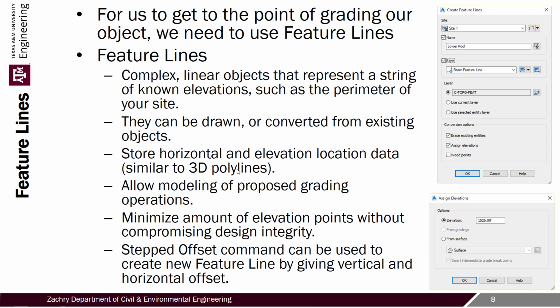So how are we going to do this? Well, whenever you're doing gradings and whenever you're doing surfaces, one of the things that you can use when you're creating your own surface is going to be feature lines. We actually had an example of using feature lines when I was talking about surfaces. We used them as break lines, and that is what we were able to create that one shape with in the examples. That was prior to spring break, so, you know, pre-corona. And so we had that video on that, and we used feature lines.